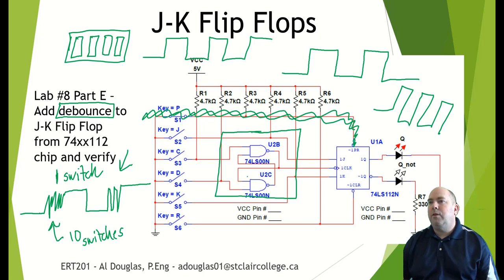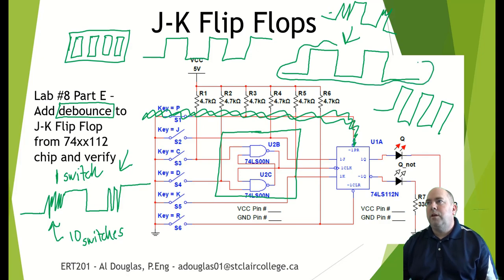So what we can do here is when we have this as our clock signal, this will read as when you transition, it takes a chattery signal like this and turns it into a nice clean signal that looks like this, which gives nice accurate counts.